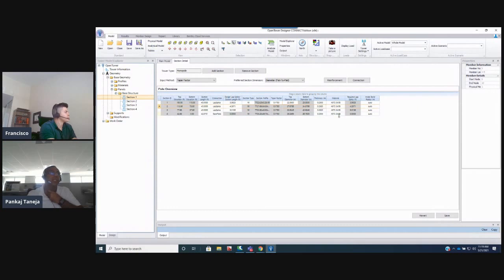We have thicknesses, and they vary most of the time. Let's say I'm just going to put this one as 0.375. These are standard plate thicknesses I'm using. In the industry, based on my past experience with poles, I have seen from 3/16 all the way to 3/4 inch thick plate. After that, it gets a little bit difficult to bend the plate, as well as to seam weld it. So I have seen 3/4 inch, I would say very rarely, but I know that half inch is very common.